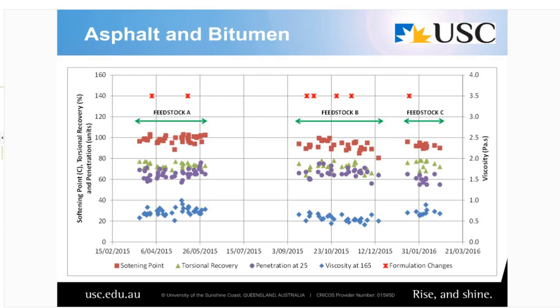There was an airport in that side of the country, the western half of the country, that did that not so long ago, and within 2 years of resurfacing their runway with what they had traditionally got good performance out of, standard unmodified C320 bitumen, they resurfaced a third of their runway because all their grooves had closed, for no other reason than because their grooves had closed. And that was, I have no doubt, significantly impacted by the absence of polymers in their binder.